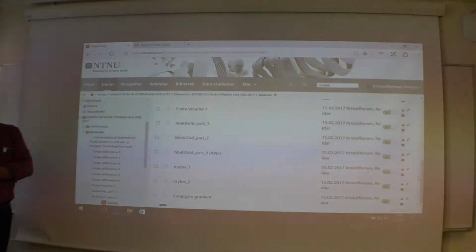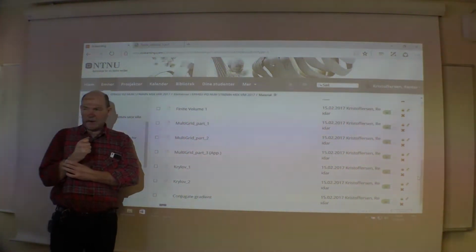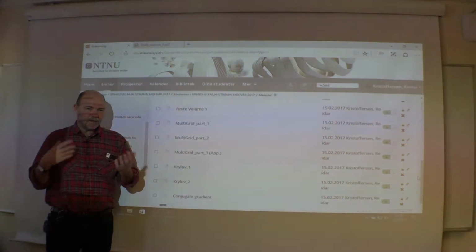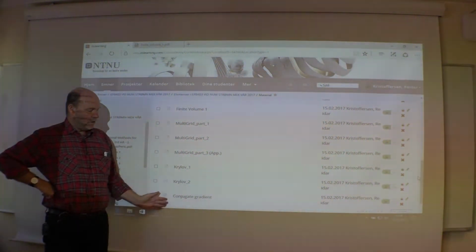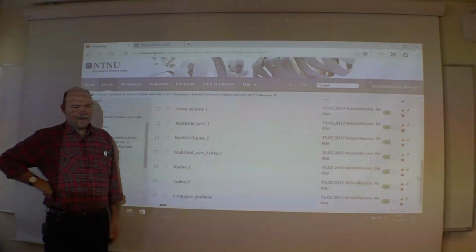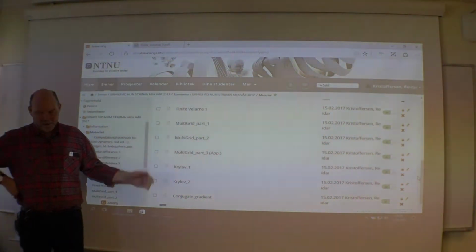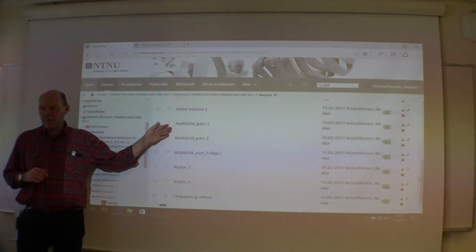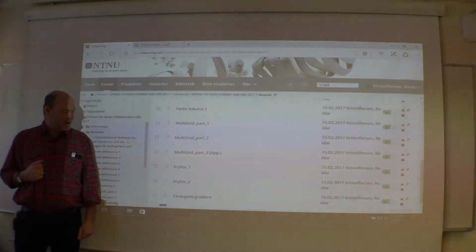Also, of course, you have direct methods. But in practice, for big problems, you can't use direct methods. You blow the memory in any computer. So you are left with an iterative scheme, and then it will typically be either multigrid or Krylov. And I believe that a user of CFD should be familiar with these methods. You should know, when your computer code asks what different parameters you are going to put into your multigrid version, what they're talking about.